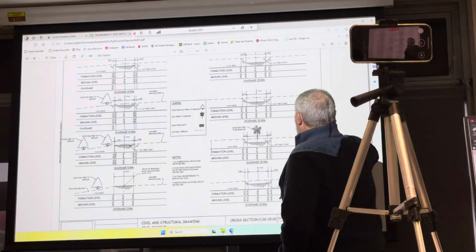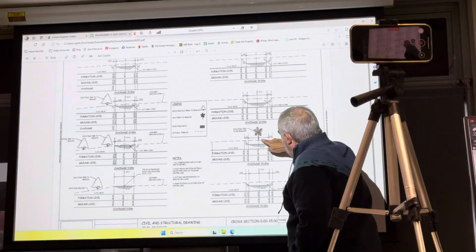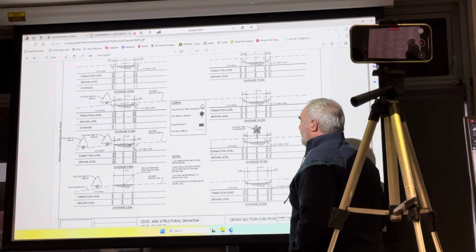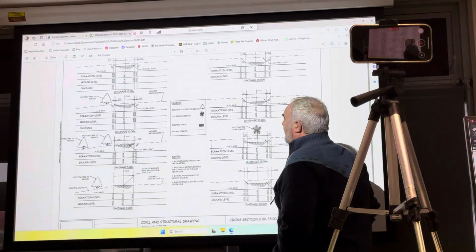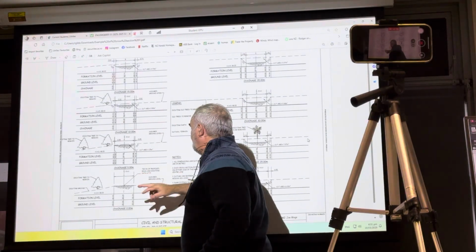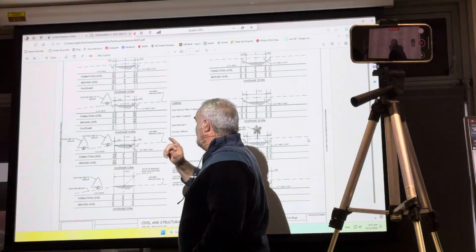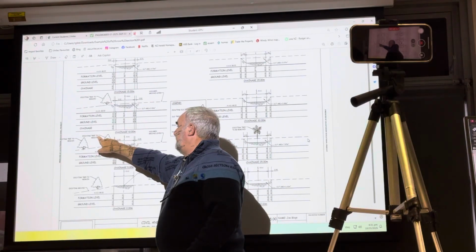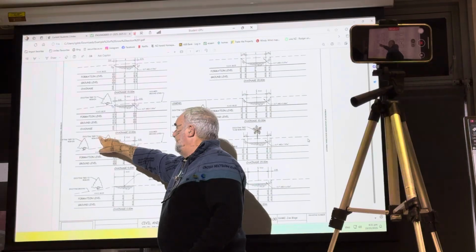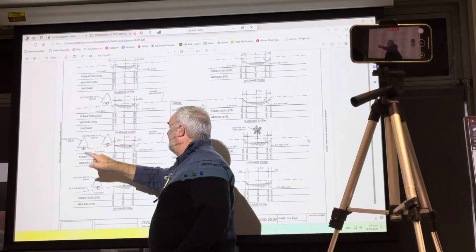The dash line should be a solid line with the hatch dashed across here. In this case, nearly all of it is cut, and I don't see the word, oh, there is cut here. So they have used the word cut in a few places. You'll know from your CAD standards on your very first CAD class, which is level 1, that is not acceptable in anything to do with the engineering.